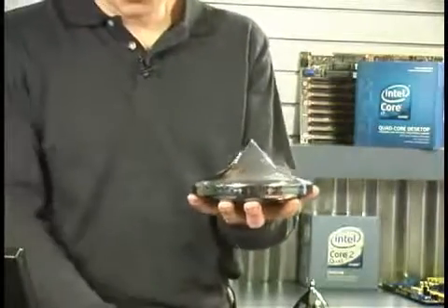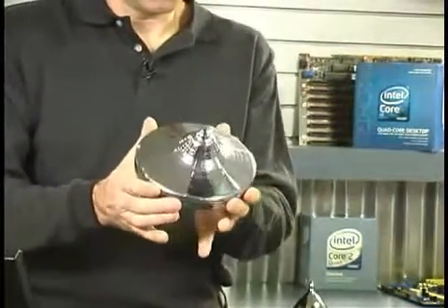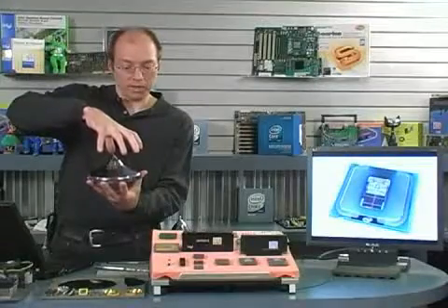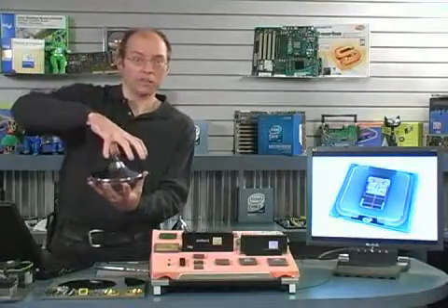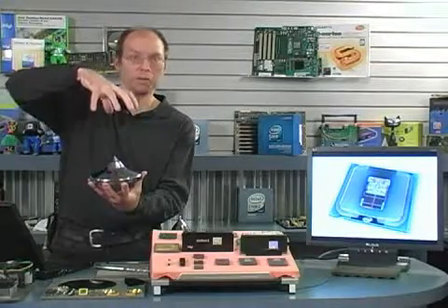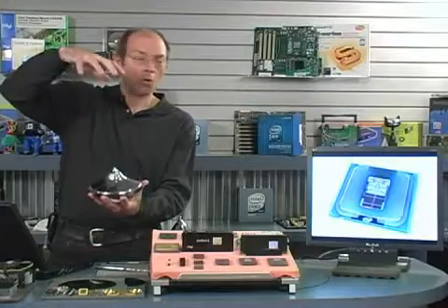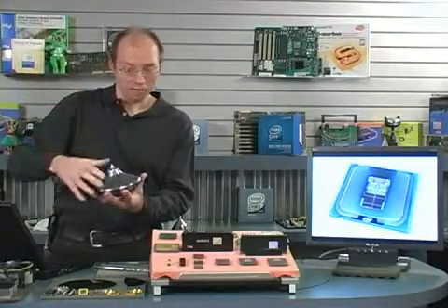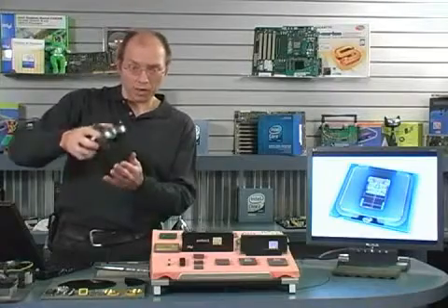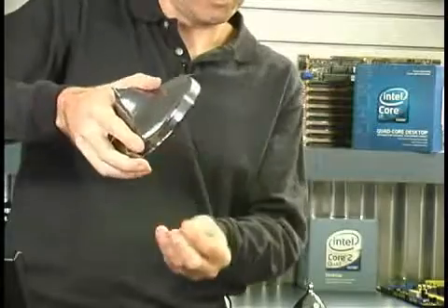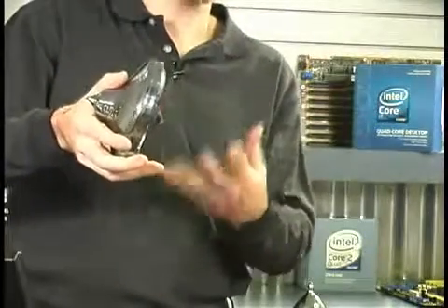Now, once the crystal reaches the diameter that it is intended to be, then the process speeds up a little bit. It's pulled out a little bit more quickly until basically what we have is like a cylinder. Imagine a cylinder of this crystal material being pulled out of this vat. Once the cylinder has reached its final length, which is usually a couple of feet long, then the pulling process goes more quickly and we end up with a tail. They want to have a gradual pull out of the material from the vat to prevent any kind of thermal shock.